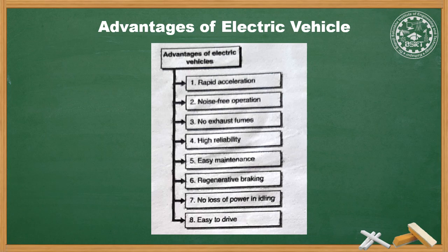The disadvantage of an electric vehicle is that its range is limited to about 100 to 150 kilometers because of the need to recharge the battery. The top speed is low, about 60 kilometers per hour, and the life of the battery is short, which means a high replacement cost of the battery. The limitation of electric vehicles: high acceleration by high torque from the motor lowers the efficiency due to higher loss in the form of motor windings and electric current.